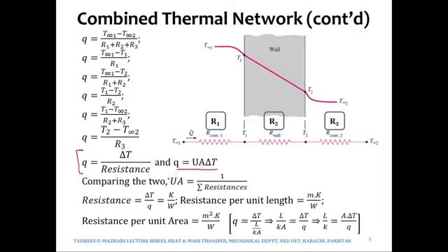So why do we call it in fact overall heat transfer coefficient? Why do we call U the overall heat transfer coefficient? Because it takes into account more than 1 mode of heat transfer, right? Over here we have a combination of conduction and convection modes, and therefore conductive and convective resistances. There may be radiative resistances as well in some future problems. There will be.